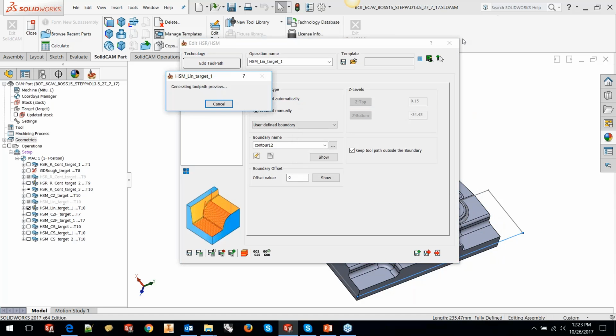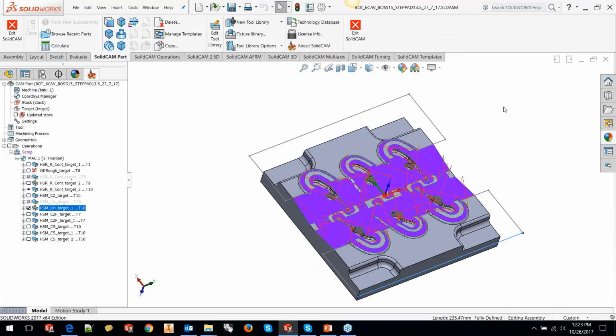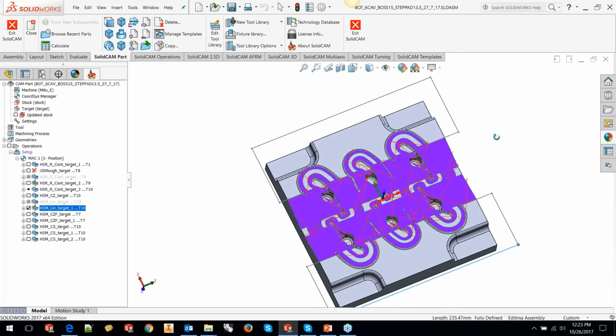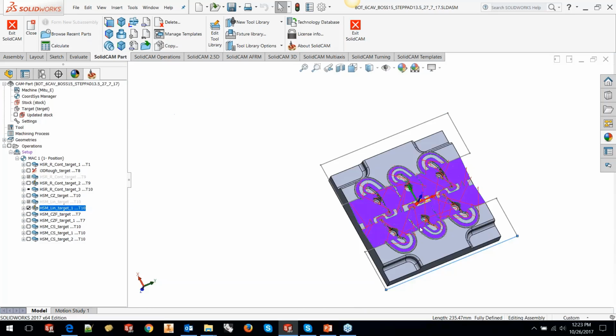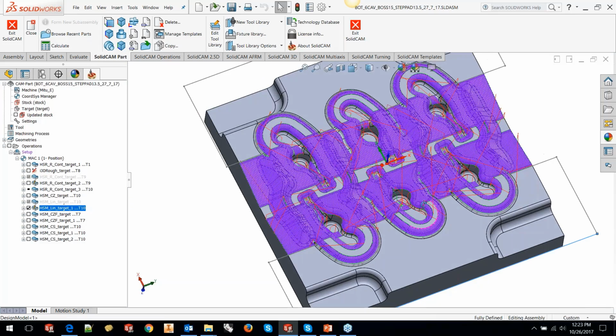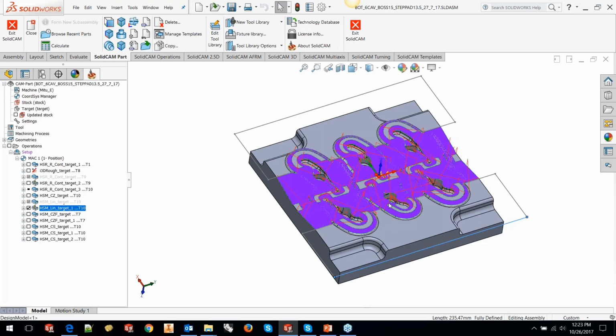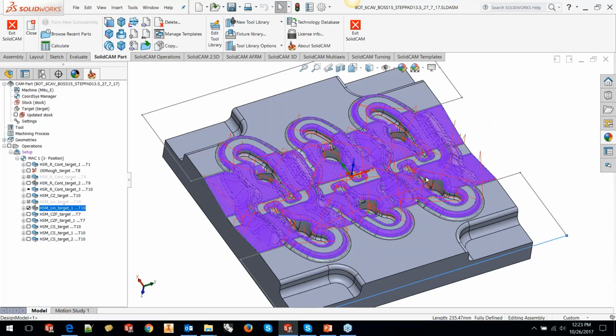Okay, that's done. You can see that the toolpath now looks much better. We chopped off all those unwanted areas, which could have easily eaten up at least about 10 to 12% of my machining time. I've saved machining time. I've saved the unwanted movements of tool, rubbing into certain areas, doing nothing. Okay, and because these motions were pretty small, the amount of time that it takes to machine those areas dramatically increases because of the acceleration and deceleration patterns of the machine.